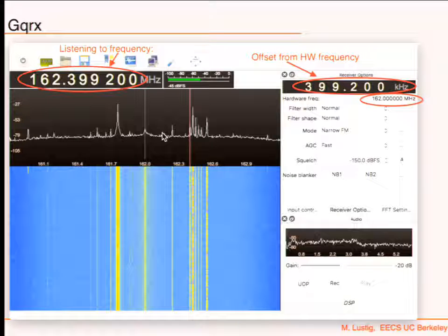Do you see here any symmetry about the middle? No. So in order to represent that part of the spectrum, I have to have complex values. Right? Otherwise, if I compute the DFT or the DTFT, I should have a conjugate symmetric spectrum. Make sense? So it has to be complex.